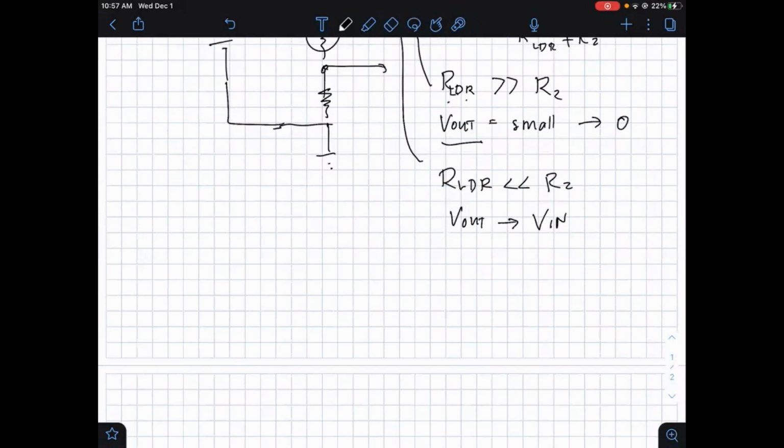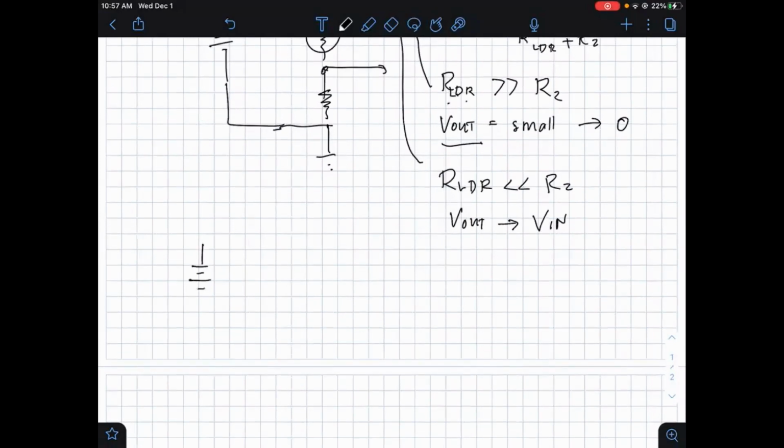Kunti na lang gagawin natin doon sa setup natin. Instead, di ba nakalagay na yung potentiometer natin? So yung potentiometer natin, imbis na yung tatlong legs niya, pwedeng kabit na lang natin dito at saka dito. And, di ba, normally ito yung 5 volts and ground, no? Ito yung signal. Pag hindi natin ginamit to, instead, nag-connect tayo dito at saka dito sa dulo, ay resistor na siya na 10 kilo ohm. Okay? So, hindi na natin siya kailangang galawin. So, parang meron tayong 10 kilo ohm resistor. Of course, we can also adjust this kung ano pa.